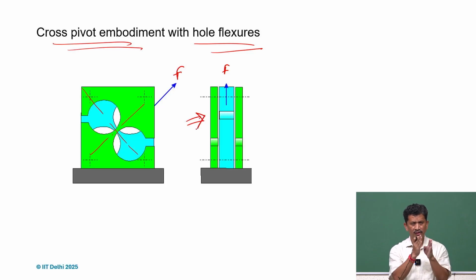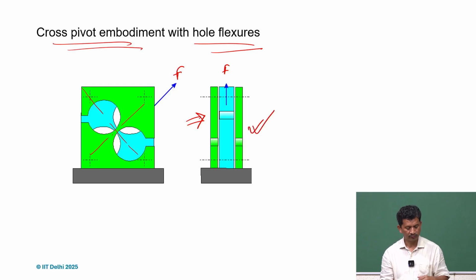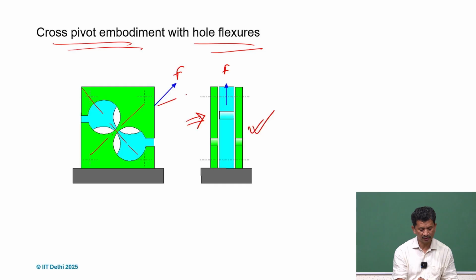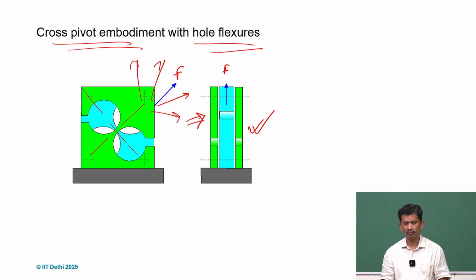We just split one of the sides into halves and put them on either side to get this sandwich structure and the symmetric design. Very good, and in this case the force direction can change in any direction. We may not have to worry because one will always take care of that load. We can write the cos and sine, resolve into two components, and it can take care of that.